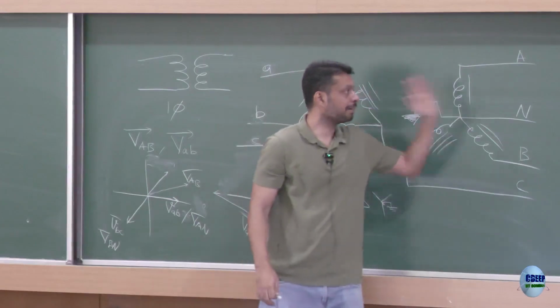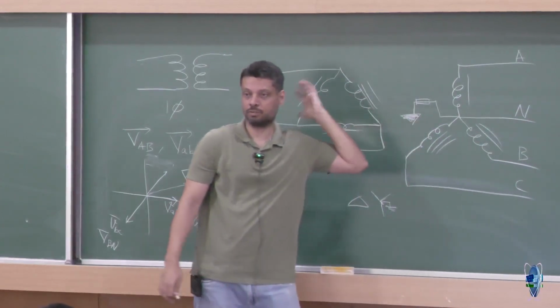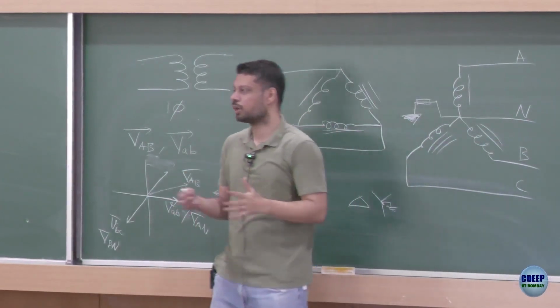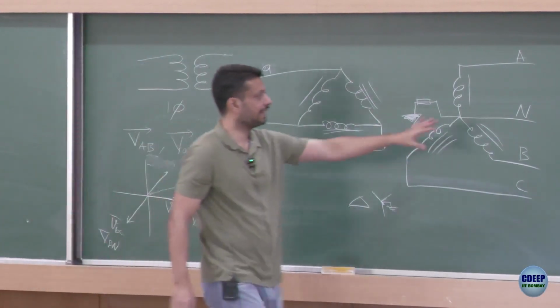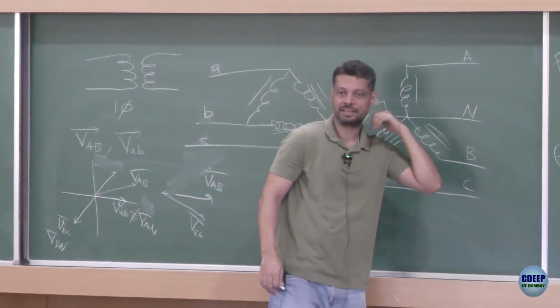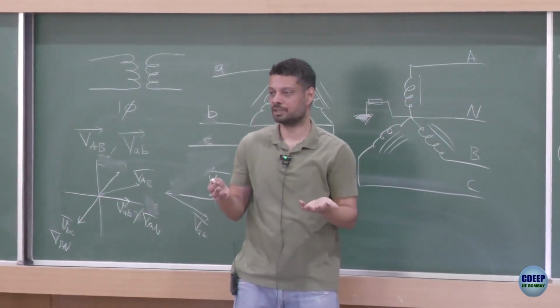Usually all the loads would be completely connected here, they would not know what is the voltage here. So in that sense, it would not really matter much if it is a 30 degree phase shift, right, because while sitting here, you do not know what are the voltages at 11 kV in a way, you do not care about them too much.